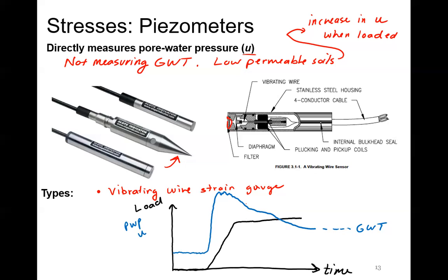And Tess, your question was how long does it take? This whole rate here is the important part. The rate at which pore water pressure dissipates tells you how long you need to hold this loading constant. Because once we reach this zone of the groundwater table, then usually all the compression has occurred and we can remove the soil that way. So piezometers and pressure plates are two really big things that you'll come across in geotechnical engineering.